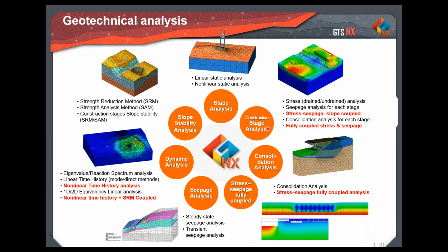And in the construction stage analysis, we basically need to go for construction stage analysis in most of the conditions, because soil is such a non-linear material, and as the stress changes its behavior changes. So in order to consider that particular condition, we need to go for construction stage analysis. And in this construction stage analysis, all the other types of analysis can be covered.